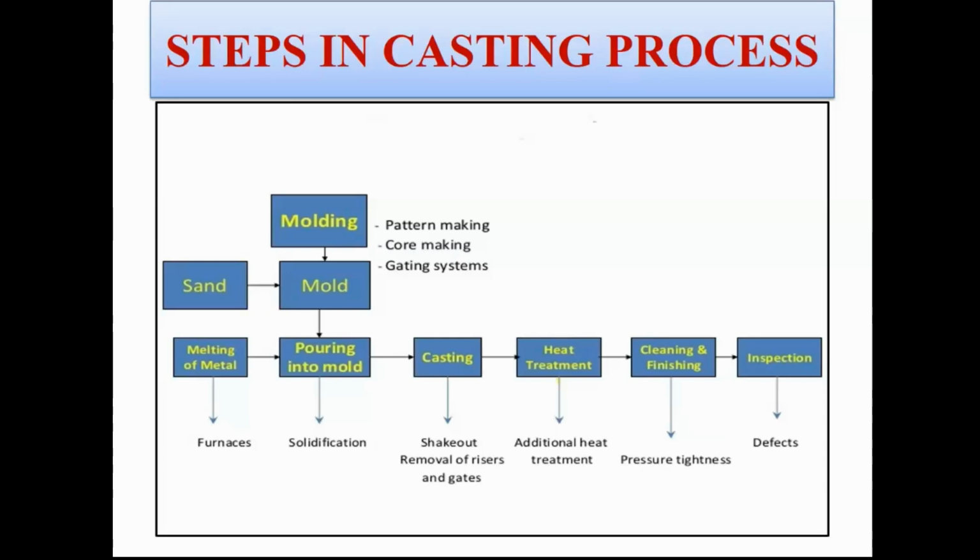So we have learned ultrasonic inspection. We have also learned about radiographic inspection, magnetic particle inspection, and dye penetration. You all know that castings can have defects similar to those present in welding, such as porosity, formation of cracks, or any discontinuity in the material.